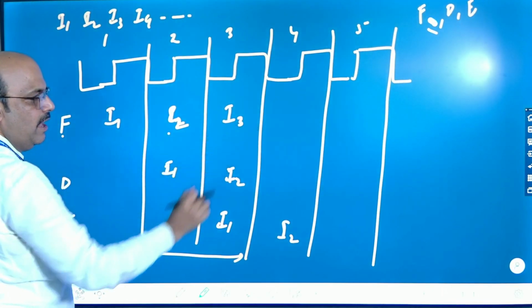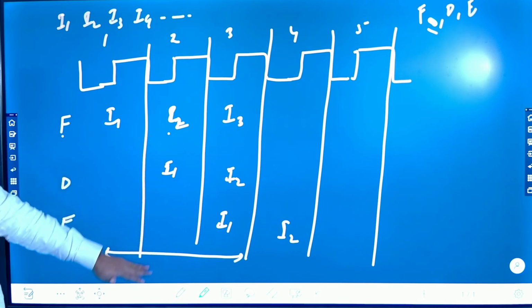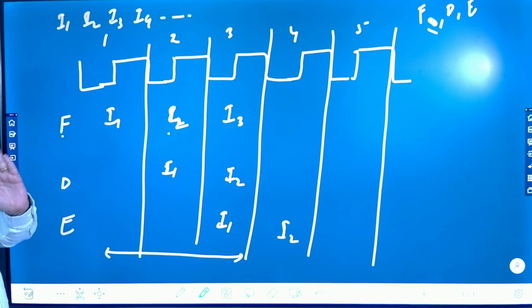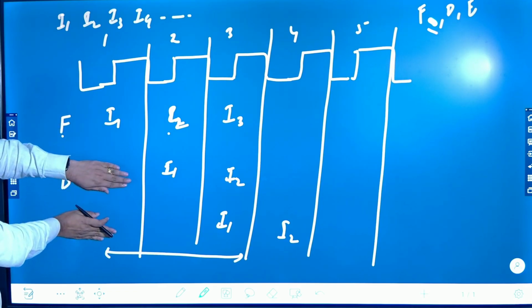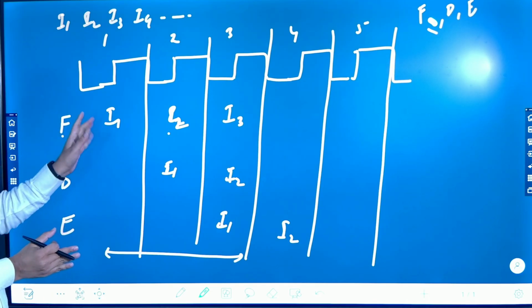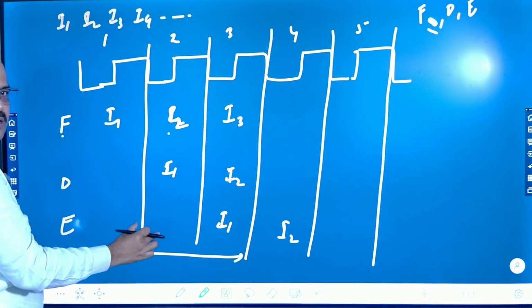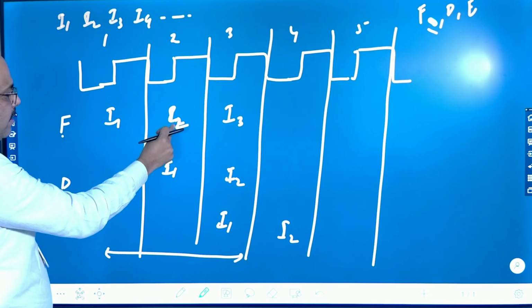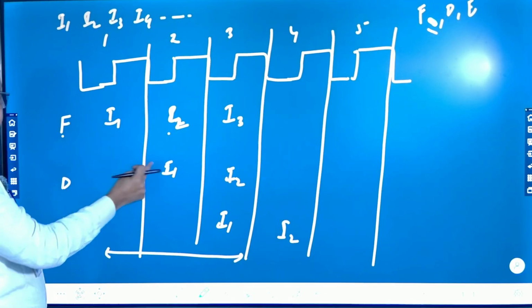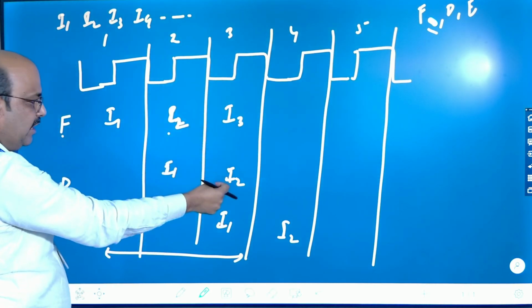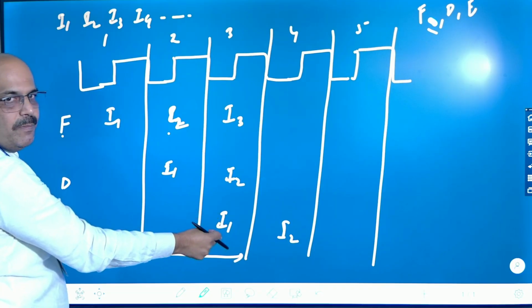This is fetching, but if you remember or you can understand from this, for the first cycle only, we consider there is no instruction in the queue before execution. That's why this part is not empty, because this is a past instruction actually, but we are starting from here, that's why we consider this one. So in the second cycle there are 2 operations going on. One is fetching of I2 and decoding of I1. For the third one, fetching of I3, decoding of I2 and execution of I1, right?